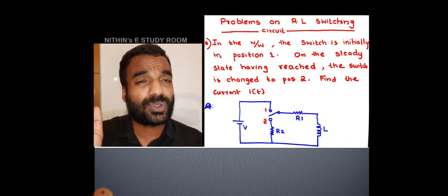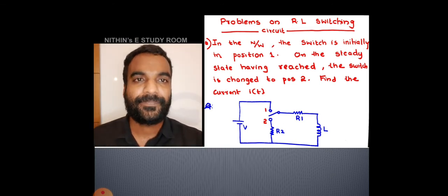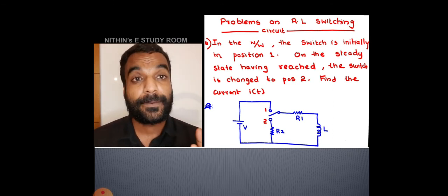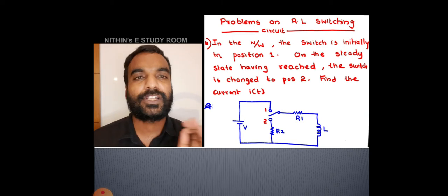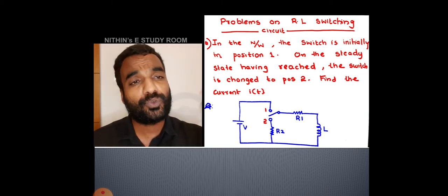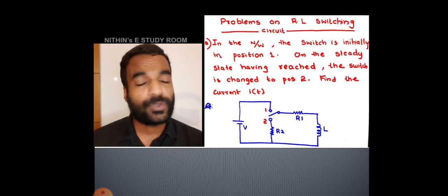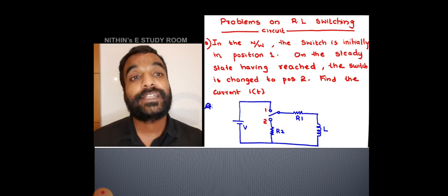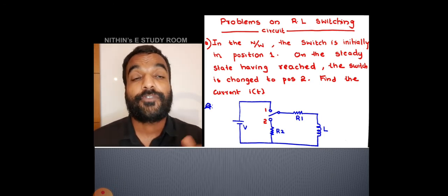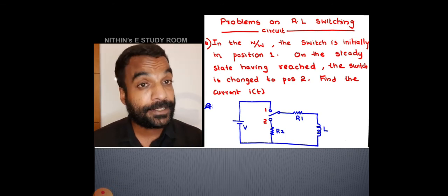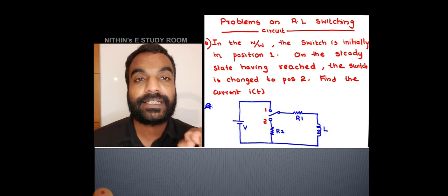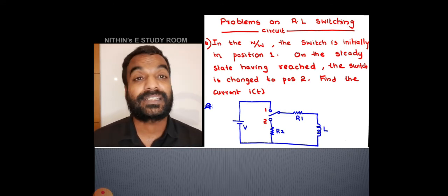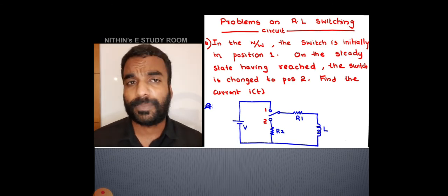These two lectures contain only standard derivations, such as how to charge a capacitor and how to discharge a capacitor, with capacitor and inductor. But in a problem it will not be exactly like that. We have to find the current expression and voltage expression. You can use the exact equation that you obtained in the derivations. So in each problem you have to develop the function of current and voltage. For that, the steps that you followed in the RL circuit and RC circuit derivations are very important. The same steps we will be applying in all problems.